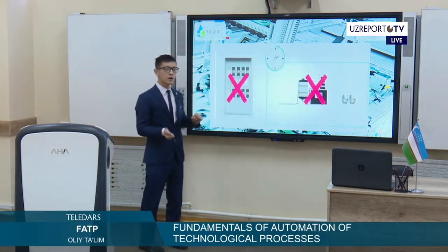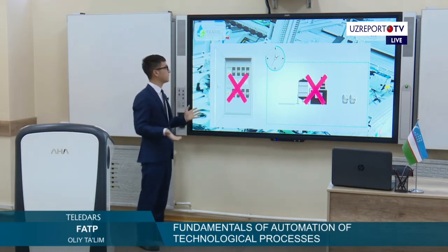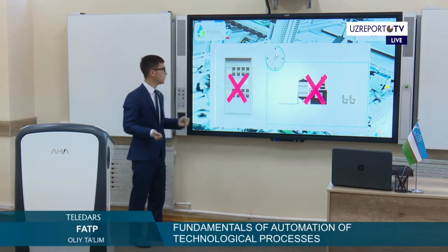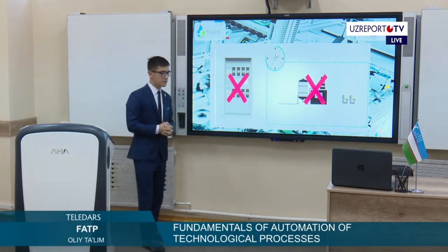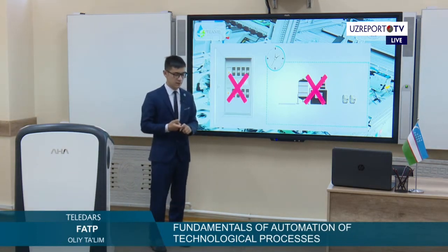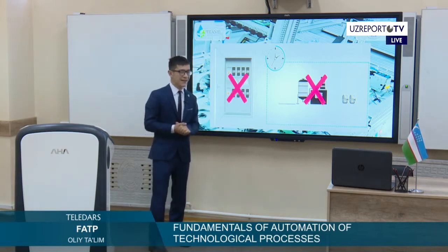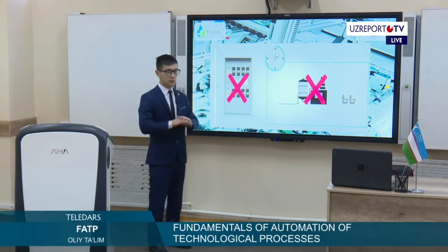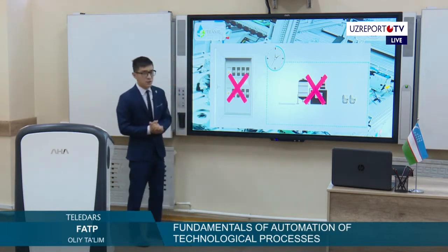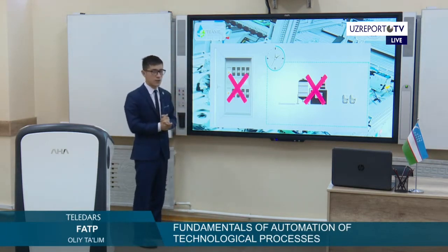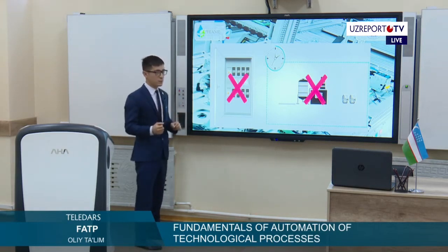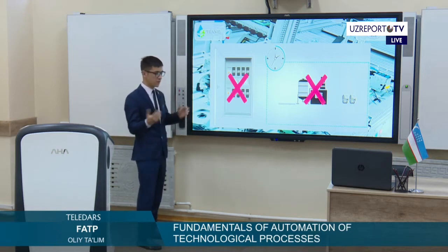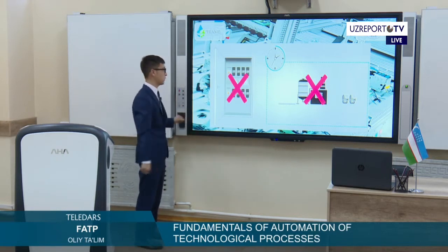In short, the reason why manufacturers now don't use relay control schemes is reliability. Unfortunately, classic relays work on magnetic contacts, and no one can predict when they will fail. That is very dangerous in big facilities like power stations or chemical factories. It is an accidental and dangerous situation. So, because of this, technological processes started to use controllers.